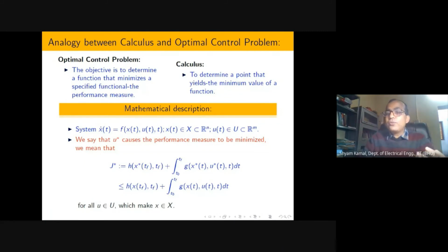And if you see the notion of controllability, you can see that it is very much inclined towards the optimal control problem. Why? Because whenever we are talking about controllability, at that time we are also specifying the time: in finite time, whether it is possible to move from one point to another point. But most of the time we are just using an asymptotic controller. Here, whenever we are solving the optimal control problem, you can see T0 to Tf, I am specifying the time. Obviously, optimal control is also possible if Tf is infinity, which means that I have an improper integral.